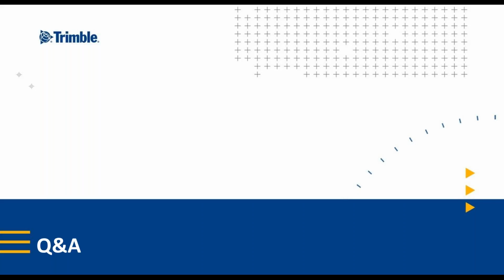Application question from Mark regarding deformation analysis. This tool was set up in a very much geospatial context. So coming off of known control and using your total station and theoretically a tight station setup or a resection, and then being able to monitor wall deformations, for example, settlement of that first example that David showed.